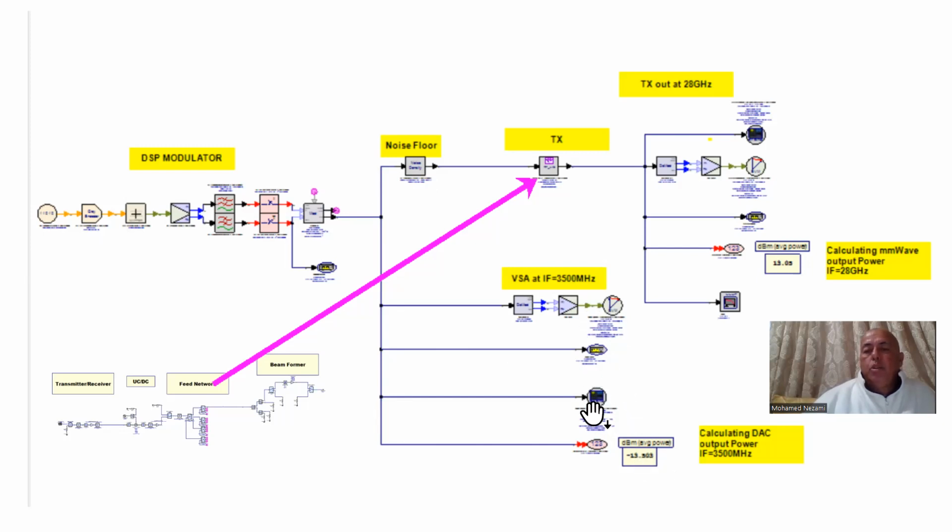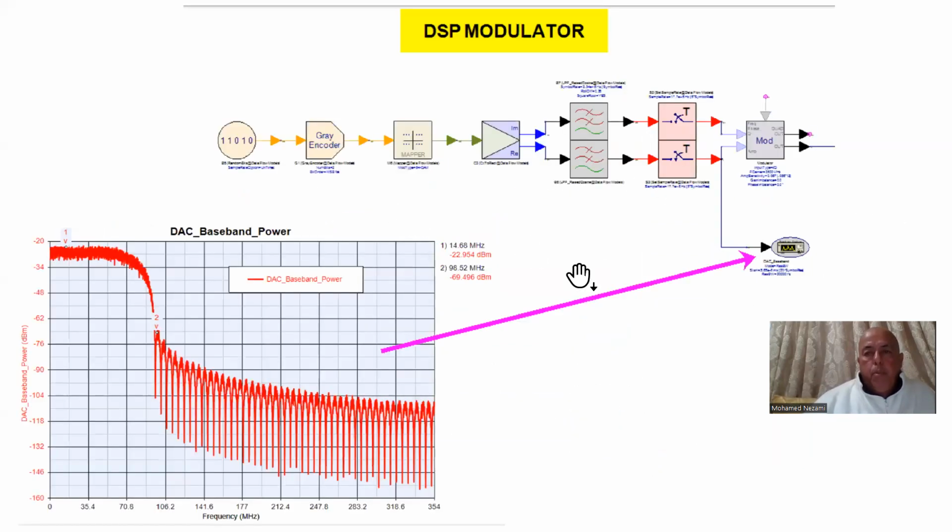So in here, I do the same thing. I look at the EVM out of the DAC, and then the spectrum analyzer and the modulation analyzer in here. So what I'm doing here is comparing the modulation integrity out of the DAC to that out of the PA of the beamformer chip in here, and that's what you're going to see shortly.